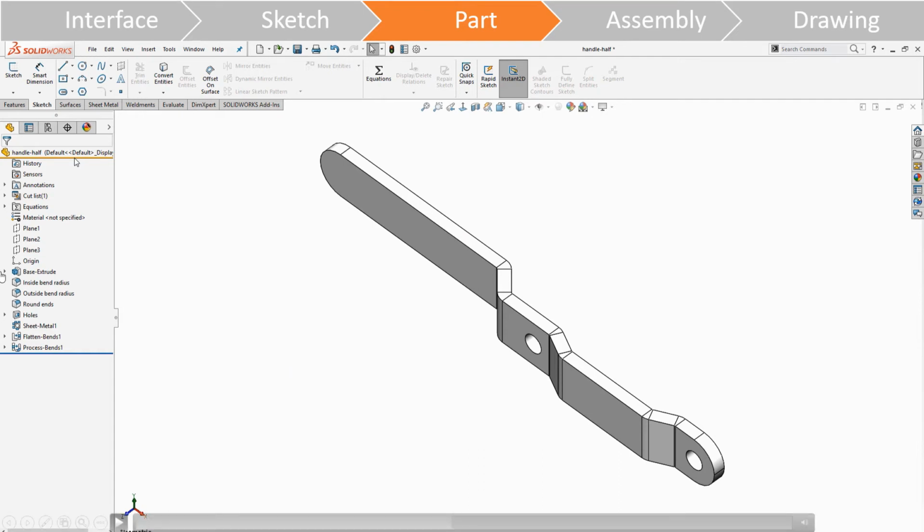Does the freeze bar help reduce time if you have a complex geometry that's just a dumb surface or solid body that doesn't really have any references, like an imported surface? If you freeze that, would that help at all, or does it really matter? I don't think that's going to. No, it's not going to, because you're not calculating. It's just still an imported body. You still have the graphics triangles, yeah.